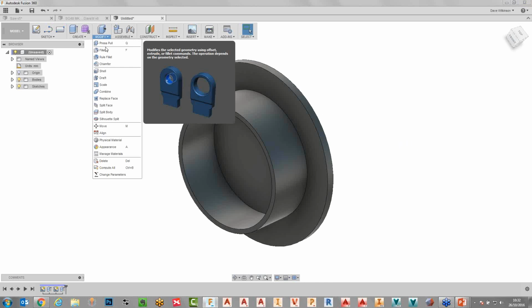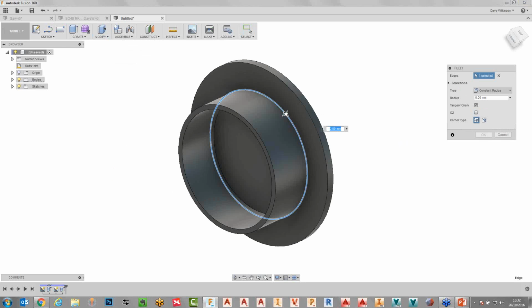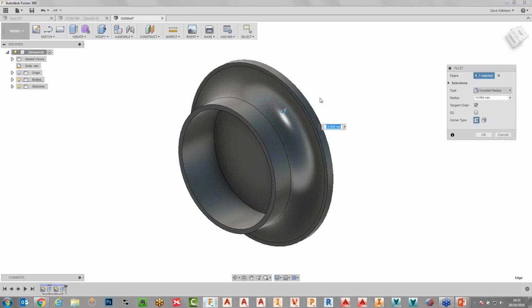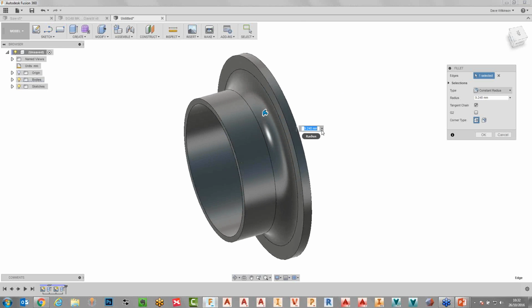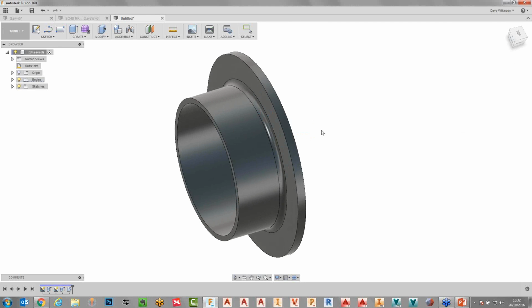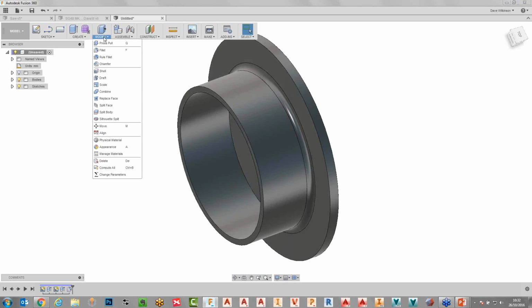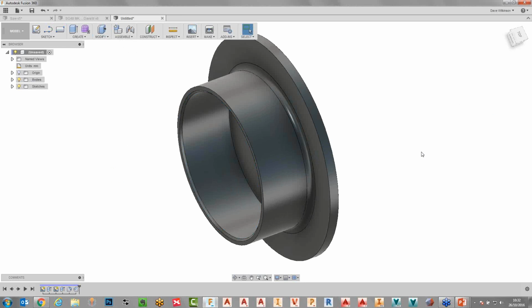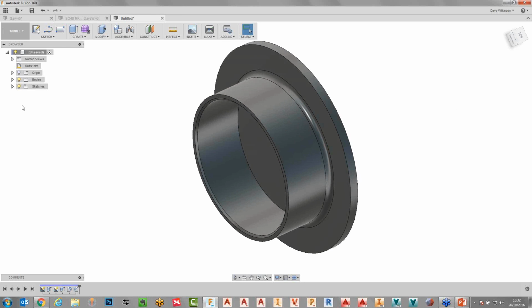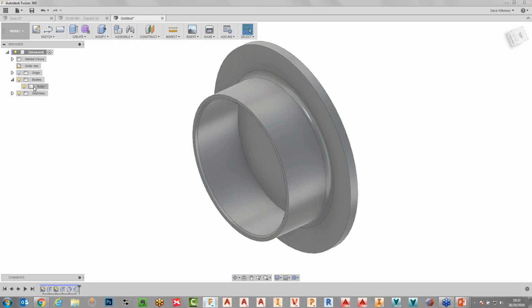From there I'm going to add some more detail to this. So I'm going to add a fillet on. You can see if I move this around a little bit, you should be able to see what's happening. Well, the point here is that it's all visual, it's very easy to understand what's being done. I'm going to choose a 3 mil radius on there, and then I want just a simple chamfer on this top edge, and I will traditionally type in just a value over here. So very quickly and easily I've produced a shape.